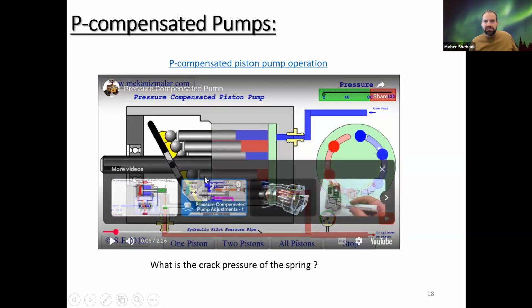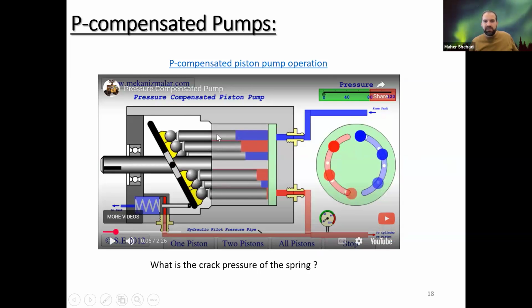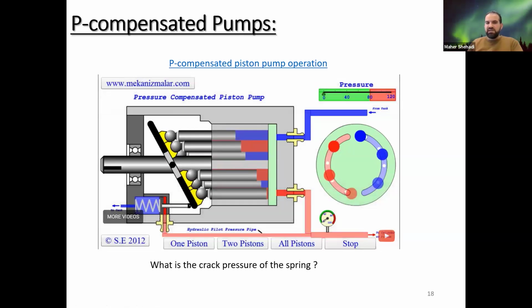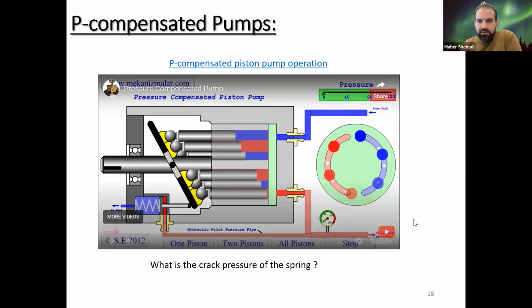before he starts clicking. We have the pump rotating here. That's the inlet. It says from tank in blue. It goes in and then it exits as red. And you have the green, once it crosses the red. He's going to play with this scale here. Once he crosses the red, that's something we don't want. I want to make sure that the pressure remains below the green, this limit right here.